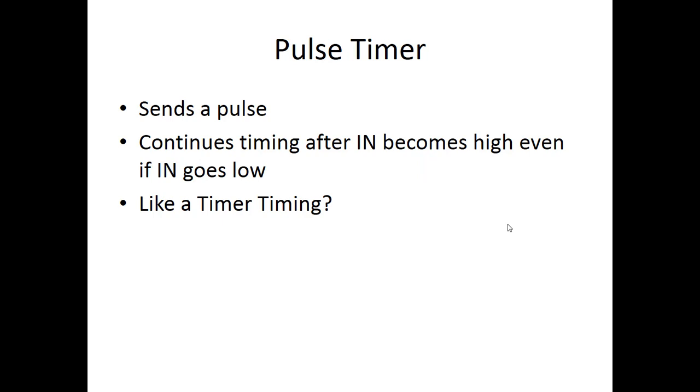Pulse timer was a little bit different. It sends a pulse. All you had to do was make the pulse timer come true for one scan, and then all of a sudden it timed. It's kind of like the off delay, where once you let go of the button, it timed, but this time it's on, not off. So even if you push the IN in the middle of the timing, it doesn't reset. It just keeps going until it gets done.